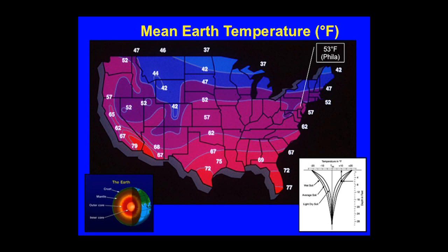And on the right, there's a graph there. I know you can't read it from there, but basically what it's saying is that the Earth temperature does fluctuate at shallow depths. So we all know you have to be beneath 3 or 4 feet to avoid the frost line, so we put these systems in at depth. Greater than 20 feet on that graph, it's showing you that the Earth temperature doesn't fluctuate. So that's why I mentioned if I drill deeper than 20 feet and shallower than 2,000 feet, I more or less have that constant temperature. And in New Jersey, it's in the 50s.